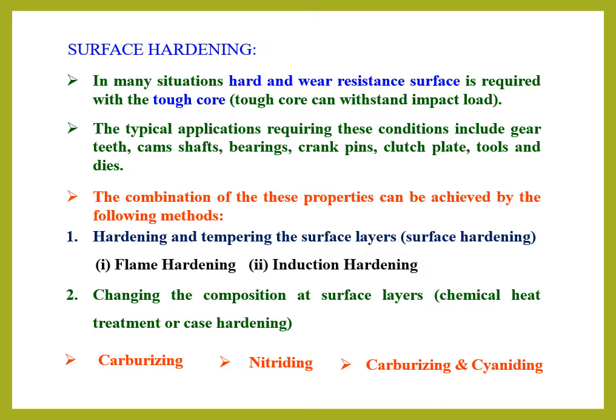Normally when we are using gears, camshafts, bearings, clutch plates and tools, all these components require a hard and wear resistant surface. Then only will they withstand sudden shock loads. Otherwise the component will fail. For this purpose we do surface hardening, so we can improve the properties of these materials.